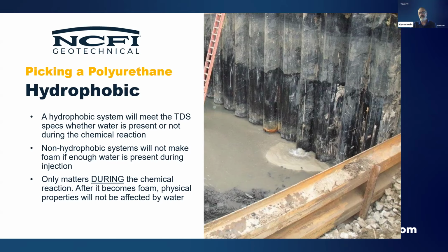Now, if you do have a non-hydrophobic system, in fact, our most popular system is not hydrophobic, the 2.8F, it doesn't have much problem in water because it's so fast. If you're trying to stop a leak with it, I've actually stopped active water leaks with that non-hydrophobic, super fast chemical. It wouldn't be good for a void fill in water, and I wouldn't use it for void filling or lifting in water.